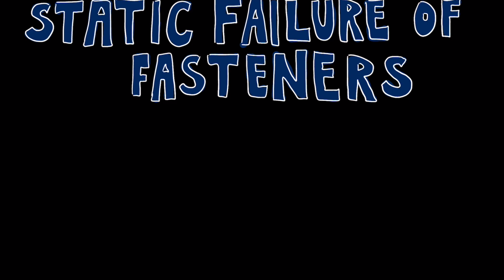To our machine design series. Today we are talking about static failure of fasteners. So we're going to develop 3 different factors of safety to predict the static failure of fasteners. The first one is simply the factor of safety guarding against our stress exceeding the proof strength.